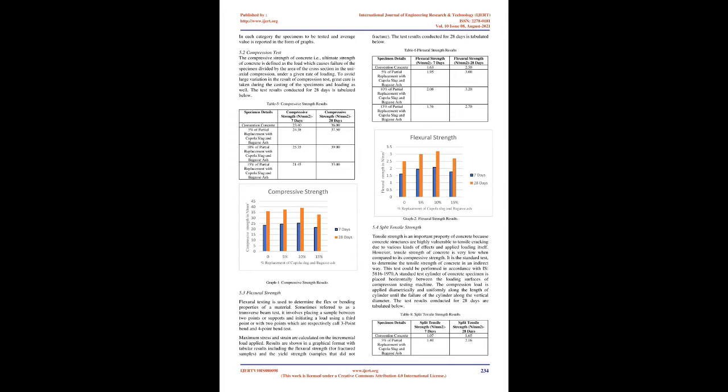Sugarcane bagasse ash has recently been tested in some parts of the world for its use as a cement replacement material. The bagasse ash was found to improve some properties of the paste, mortar, and concrete including compressive strength and water tightness in certain replacement percentages and fineness. The higher silica content in the bagasse ash was suggested to be the main cause for these improvements.